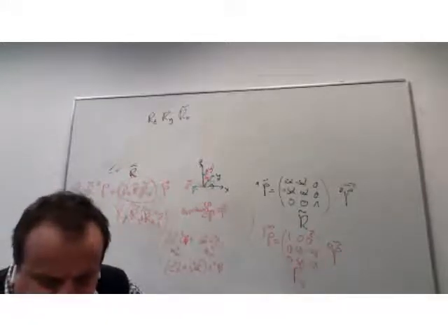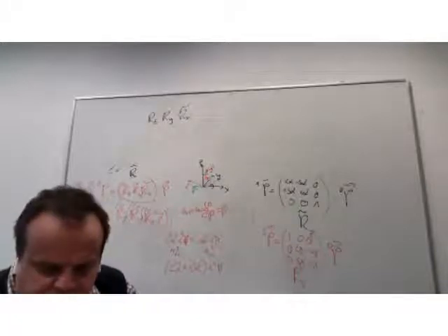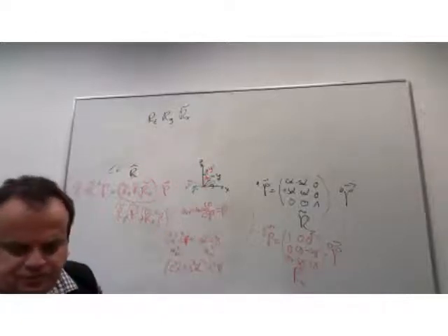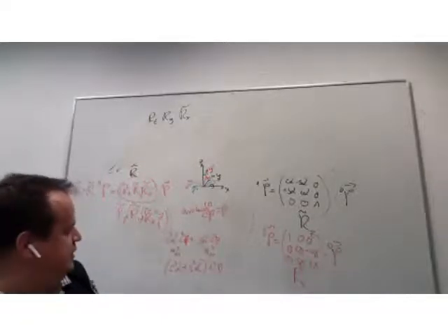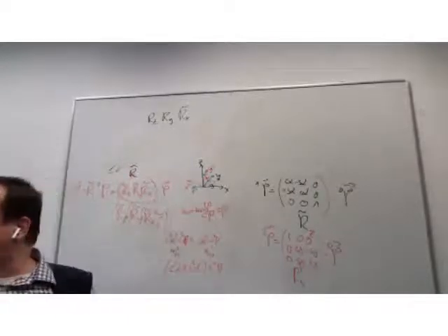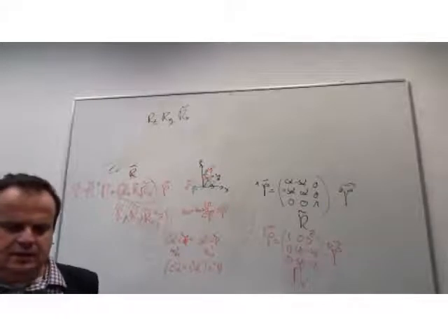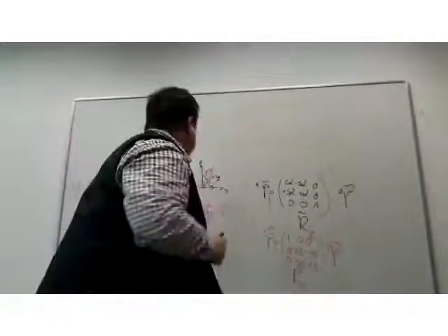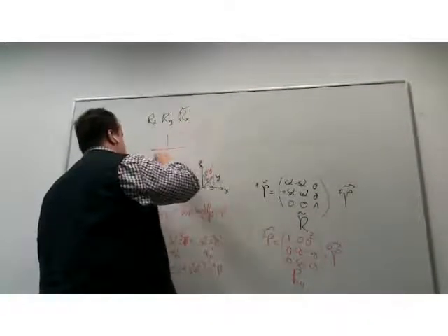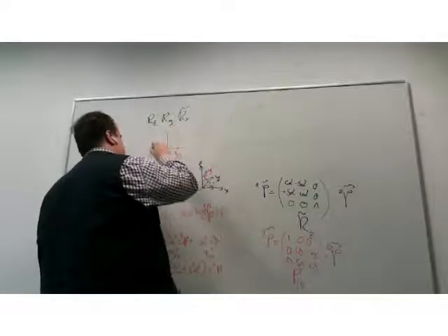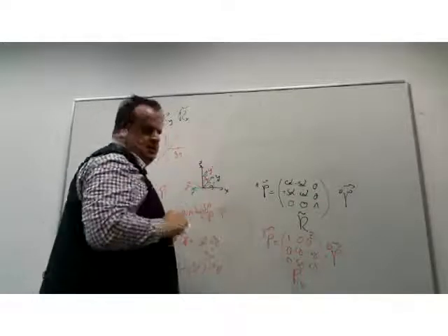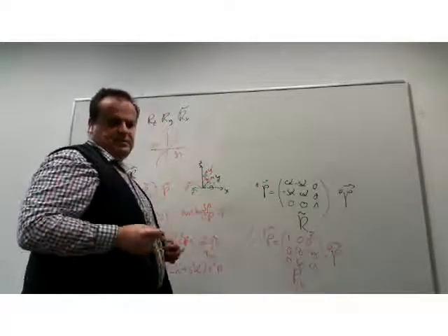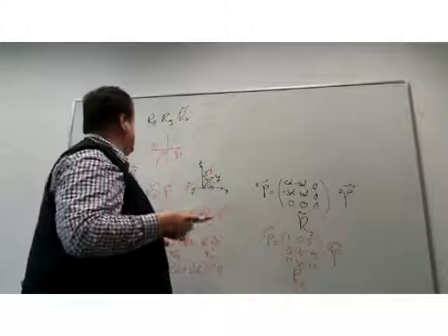So taking the minus R31 in the numerator, dividing by the square root of these two, gives me an arcus tangent expression here. The problem we are having here is that the tangent function is defined just between plus 90 degrees and minus 90 degrees. So if I would just take the arcus tangent itself, the result will span just 180 degrees.